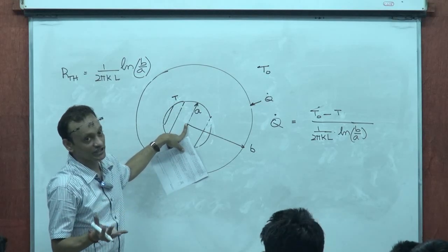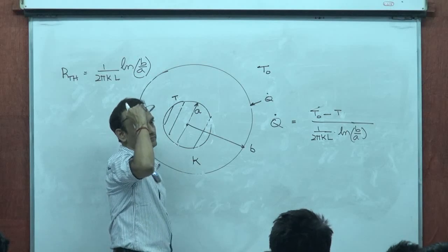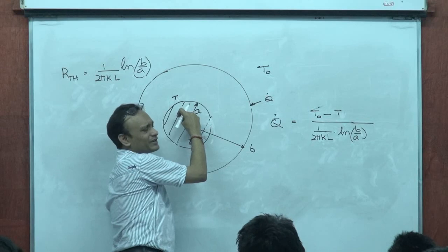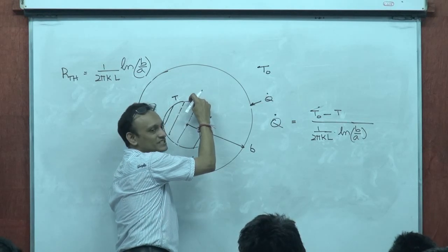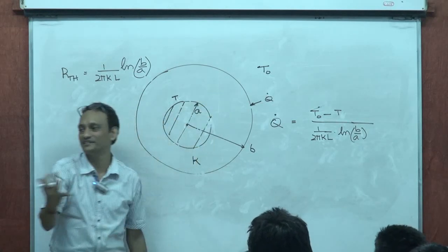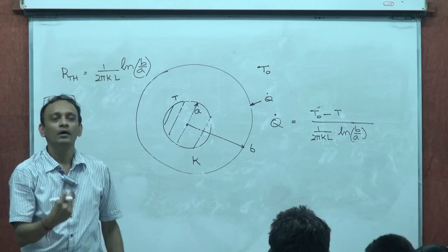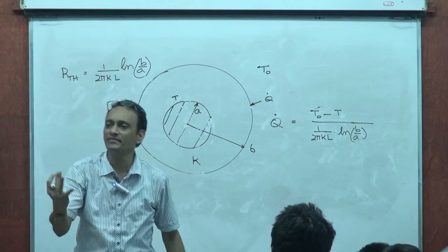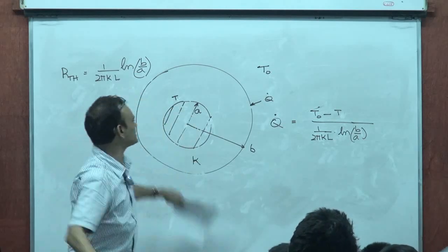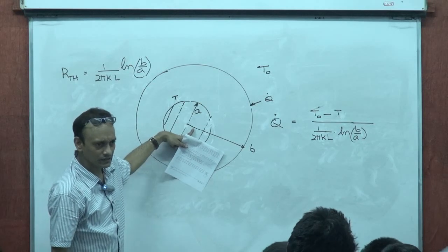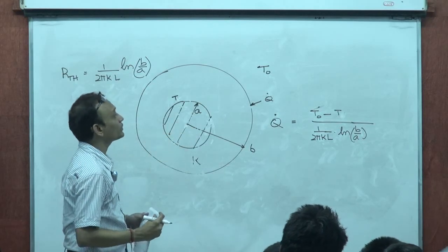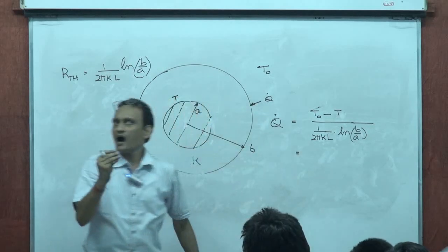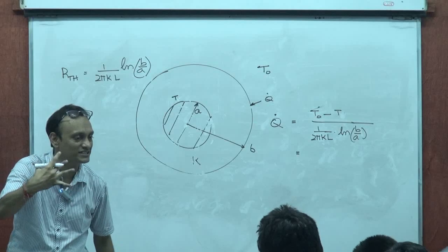Increasing the temperature of the cylinder. Now, one thing, this is heavily conducting. So, if a certain change is brought about on the skin, it's communicated to the bulk. So, at all points of the solid cylinder, the temperature at any given instant will be the same because it's heavily conducting. Now, that must be equal to the mass into specific heat, which is thermal capacity.